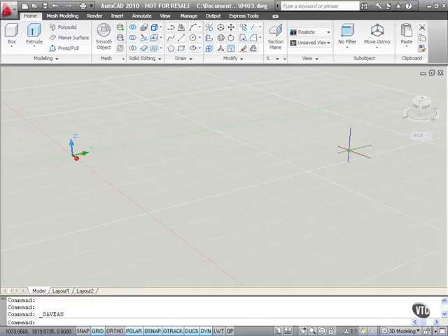What we're going to look at now is the 3D printing service available to us in AutoCAD 2010. Now what you'll notice is I'm working in a 3D drafting environment this time round, not 2D. I'm going to create a basic 3D solid, and I'm going to show you how to send it out as a stereo lithography file to a 3D printing service, an STL file. Now a 3D printing service will actually create a solid physical model of the model that you've created in AutoCAD.